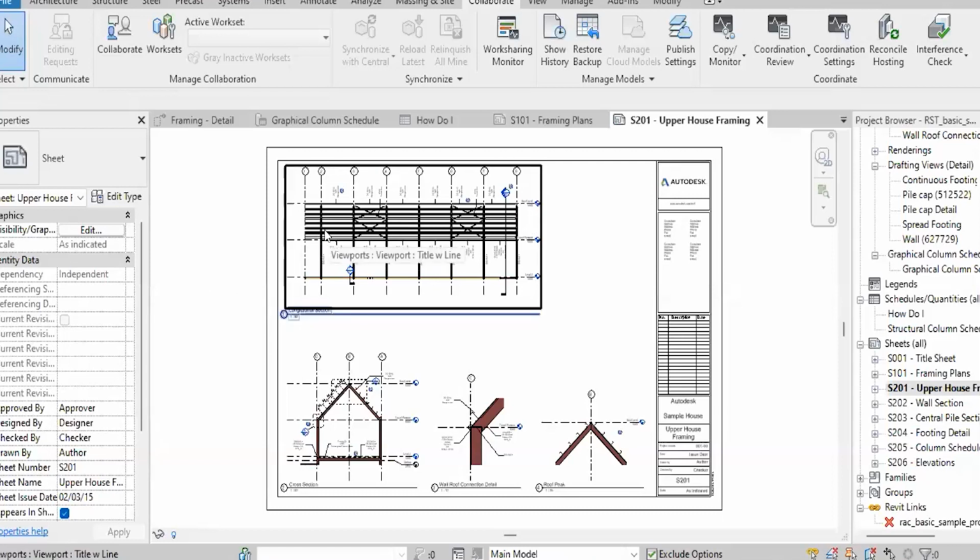So this is about the structural software that is useful for us. Actually, software orientations, everything is common. You have Stat Pro, you have Tekla, everything is common, but each has some benefits in some parts of the detailing. For example, Tekla is very well versed in steel designs, whereas Revit is better for RCC and concrete. Even though Robot Structural Analysis does a better job, people prefer Stat Pro till now because it has reached the market to that extent. The output you get is somewhat similar in all the software, up until the data that you give for a structural analysis.